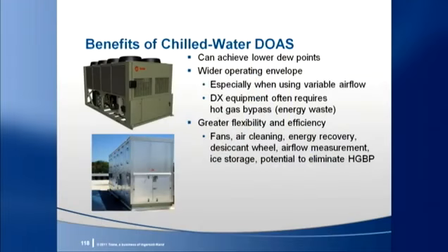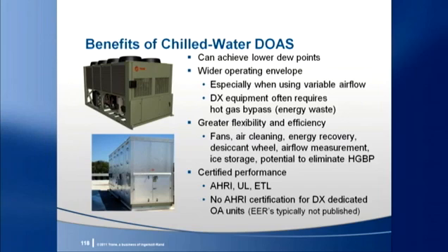Also with the chiller, you get ASHRAE certified performance, so you're sure to get what you paid for. There's currently no ASHRAE certification program for DX dedicated outdoor air units. Finally, using a chiller will typically result in a lower refrigerant charge than a DX unit. This can help achieve LEED EA credit 4.